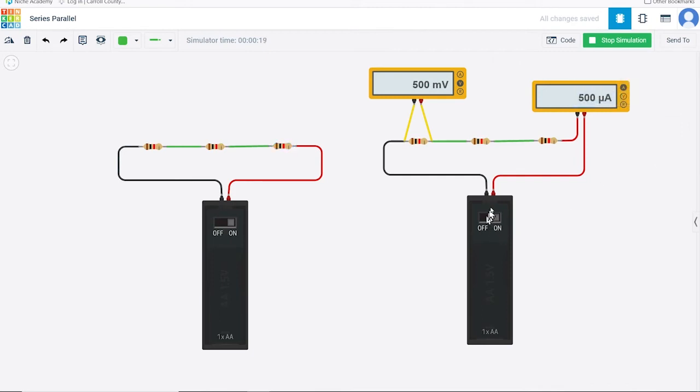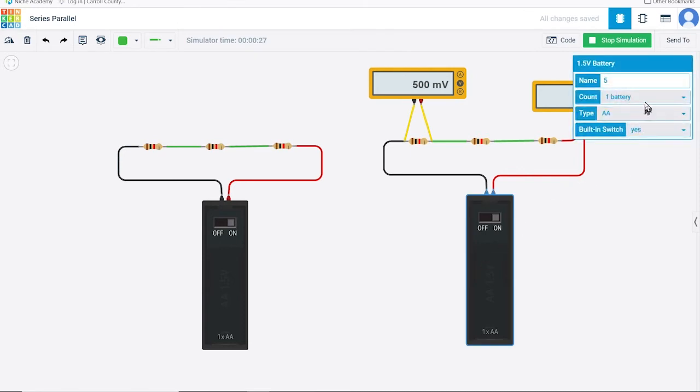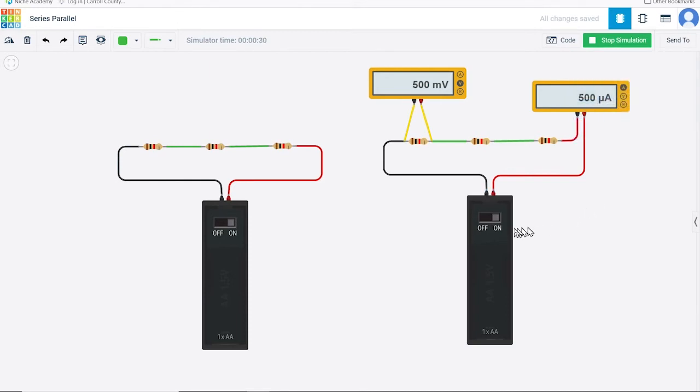On the right, we have the same circuit, except this time there are multimeters connected to measure the voltage across a single resistor, as well as the total current flowing through all 3. Note the method in which each is connected. The multimeter measuring current is in series with the circuit, whereas the multimeter measuring voltage is in parallel, and we'll talk about parallel configurations in just a moment.